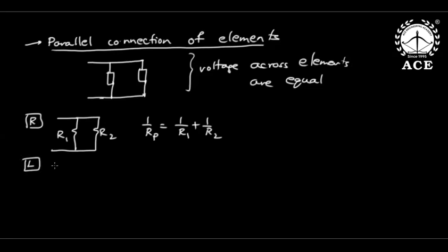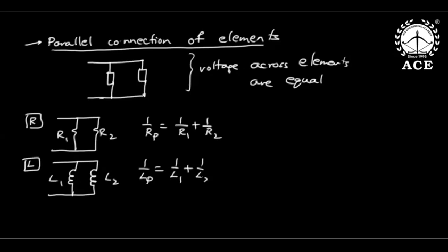Then inductors in parallel. Here also I am neglecting mutual inductance. Inductance in parallel, the resultant is again lower than the least. 1 by L1 plus 1 by L2.